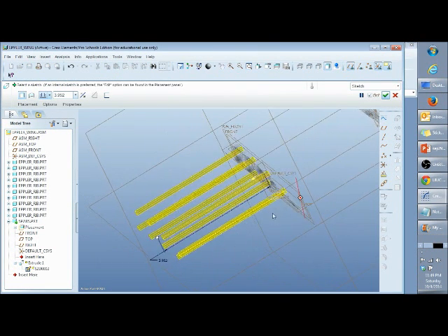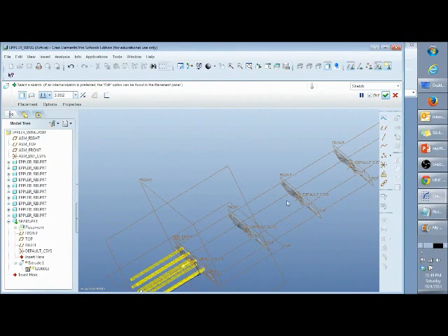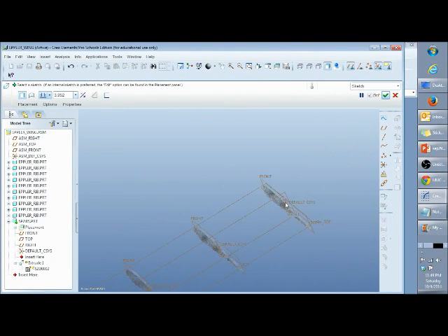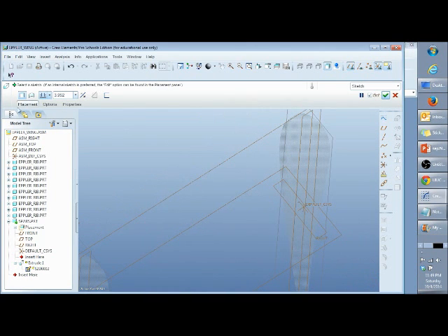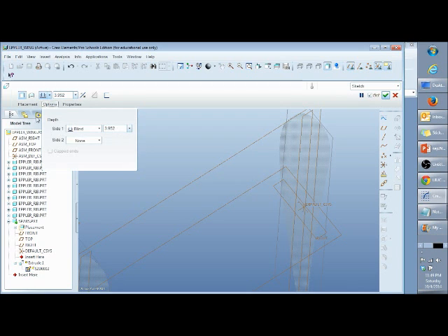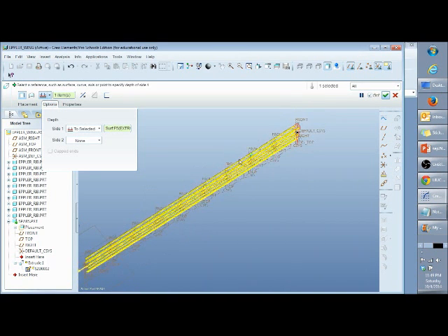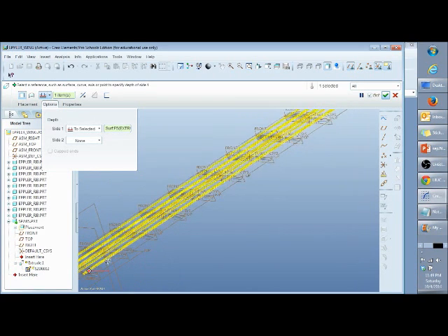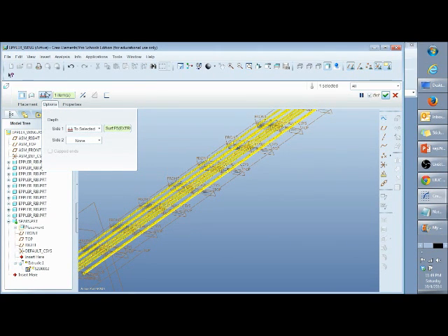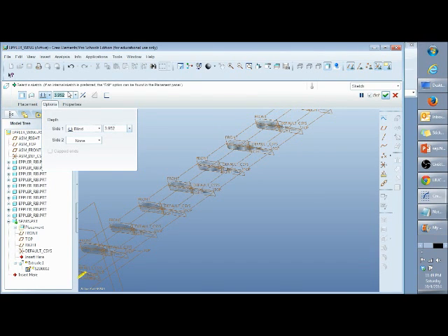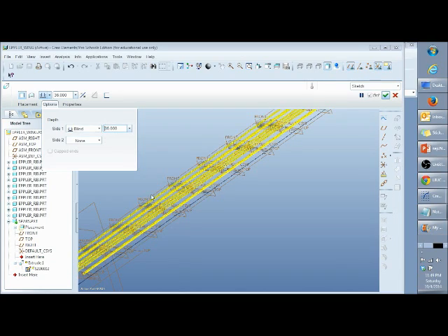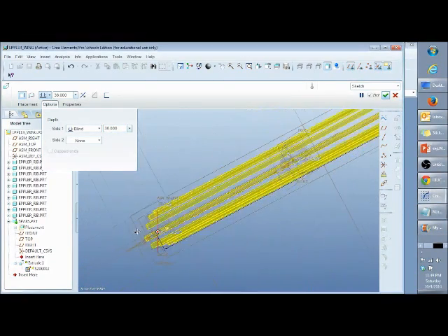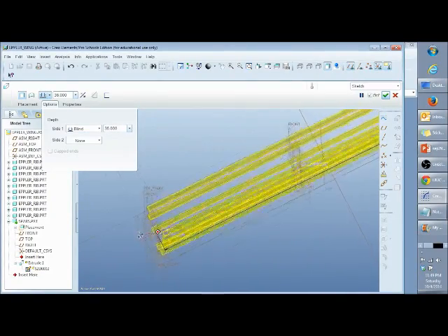Awesome. So Creo Pro-E kind of freaks out like it always does when it has parts that you shouldn't really have. I shouldn't have had those references, and it caught me before I was able to go through with it. What I'm doing now is I'm just gonna select this back edge, and select it out to, actually, I may do the same thing, so I'm just gonna do negative 36 inches. So it starts at that edge. Oh, is it starting at the inner edge?